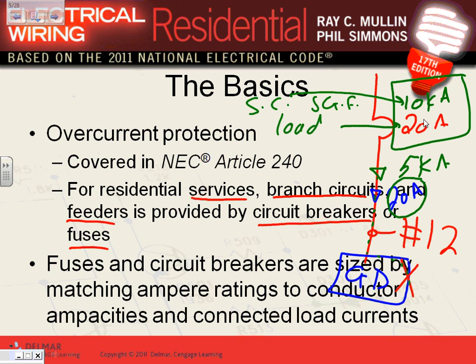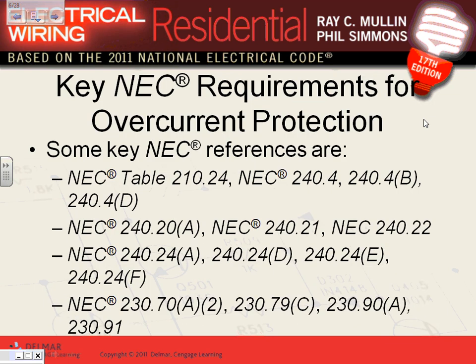Conductors have to have 2 values. One, continuously carrying the amount of current, to carry the amount of current under normal conditions. And the other one is, upon the existence of a ground fault or short circuit, would this conductor be able to continue intact without burning? Any question, guys, about this? That's what the circuit breaker is supposed to do, to protect you from mainly 2 conditions, faults and overloads. Any questions? Nick, does it make sense? And you guys have been doing this with me all the time.